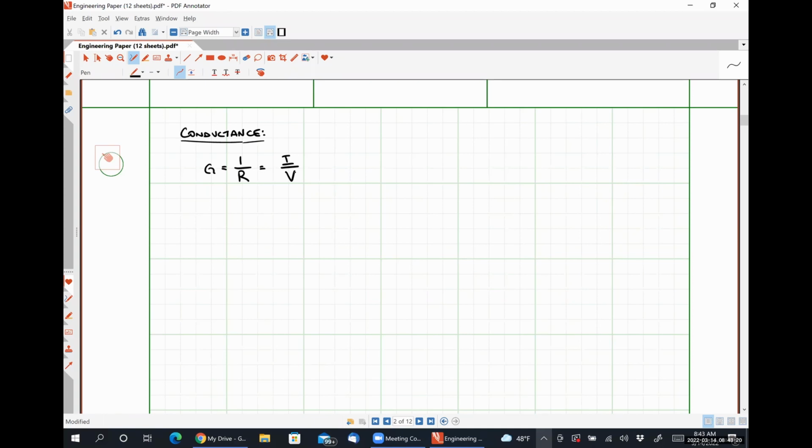There are a couple of homework problems related to conductance, so I'm going to teach you guys a trick to handle it. Take your conductance, take the reciprocal of it to make it a resistance, and then treat it like a resistor and go on about your day. Beyond that, it is completely and utterly useless for you to know the behavior of conductance. I truly believe that as an electrical engineer. The overwhelming majority of you have no reason whatsoever to care about conductance, okay? Make your life easier, convert it to resistance, and then use your resistor combination techniques that we're going to develop.